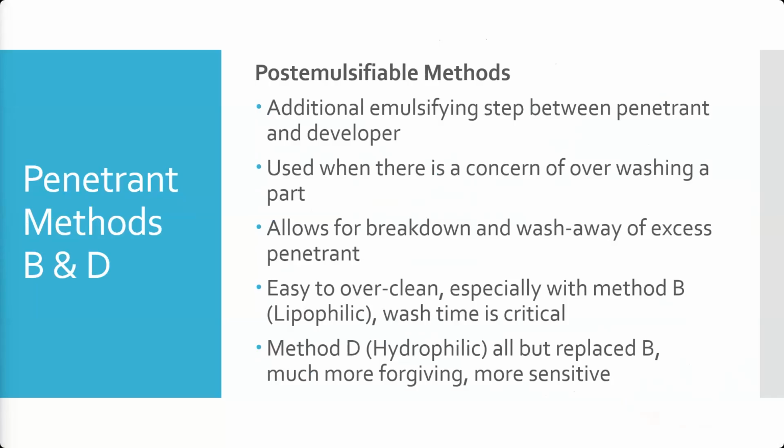So lipophilic, method B, is more strongly attracted to, and philic means attracted to, the oil molecules in the penetrant. But it's a polar molecule, so one end attracts to the oil, the other end attracts to water, but it's more attracted to the oils.